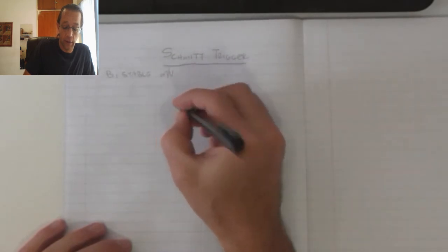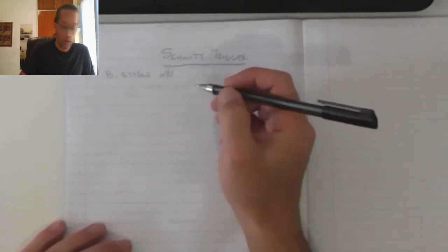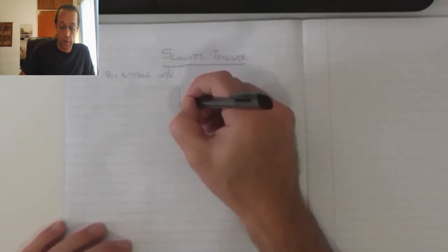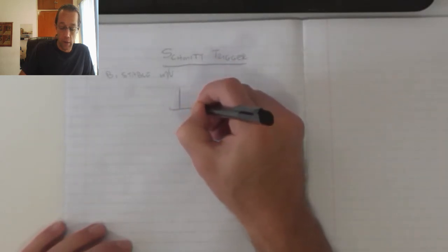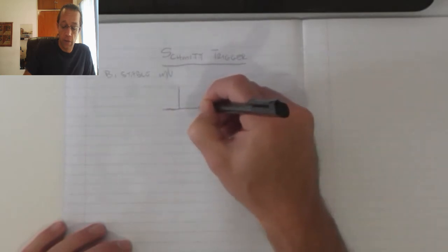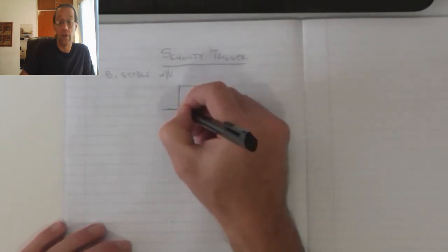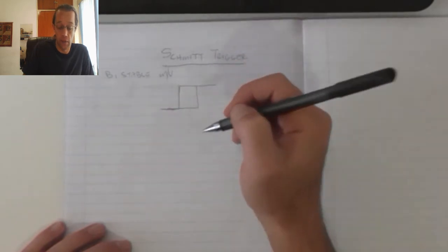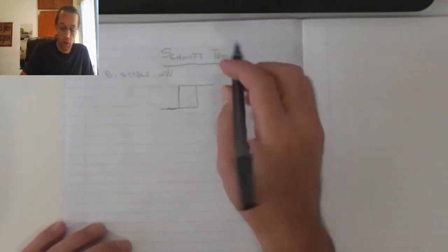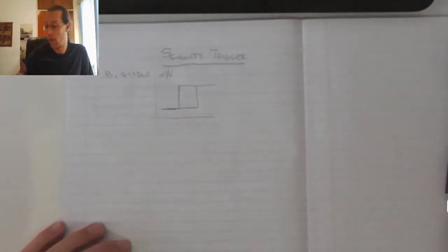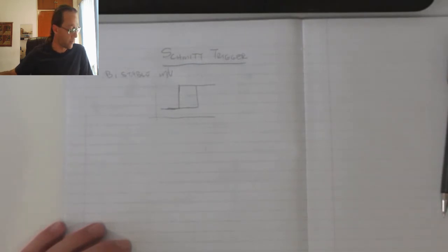This is called the hysteresis effect of my multi-vibrator, or the Schmitt trigger. This hysteresis curve, hysteresis means to lag behind, is a simple explanation of how this circuit obtains the ability to do that type of switching. Now the axis is dependent on the supply voltage and the values of the components.